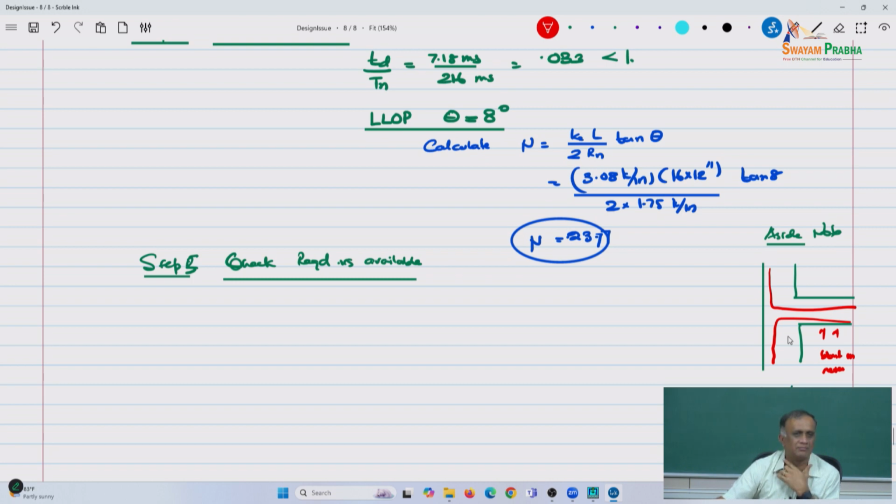There are other connection details, so that's something we have not addressed, and I'm not sure that the community, at least the private side of the engineering community, has addressed this very clearly. There's no document that I know of. In seismic, AISC has a very specific seismic design manual. A lot of the details are addressed in a clear manner. In concrete, our committee has a design guide, there are some other books available, and standards like ASCE 59-11 that talk a little bit about it, but there are no examples in 59-11. So there's a lot of paucity in literature in all these, and what they will do is punt and say use seismic principles.